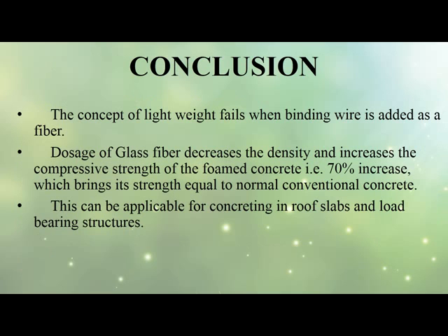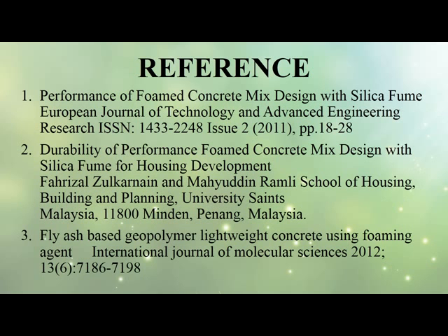Conclusion. The concept of lightweight fails when binding wire is added as a fiber. Dosage of glass fiber decreases the density and increases the compressive strength of foam concrete, such that a 70% increase brings in strength equal to normal conventional concrete. This can be applicable for concreting in roof slabs and load-bearing structures. These are some of the references of my project.